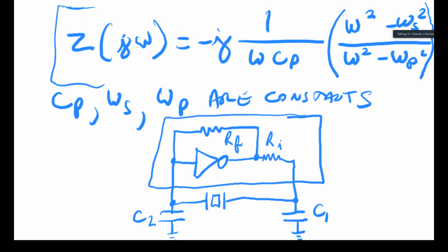So this is all implemented inside a chip, and all you get is two pins, and maybe some of you already work with that. You put the crystal and the two capacitors on the two pins, and you get yourself an oscillator, and that's called the Pierce oscillator. So probably the most widely used oscillator these days.